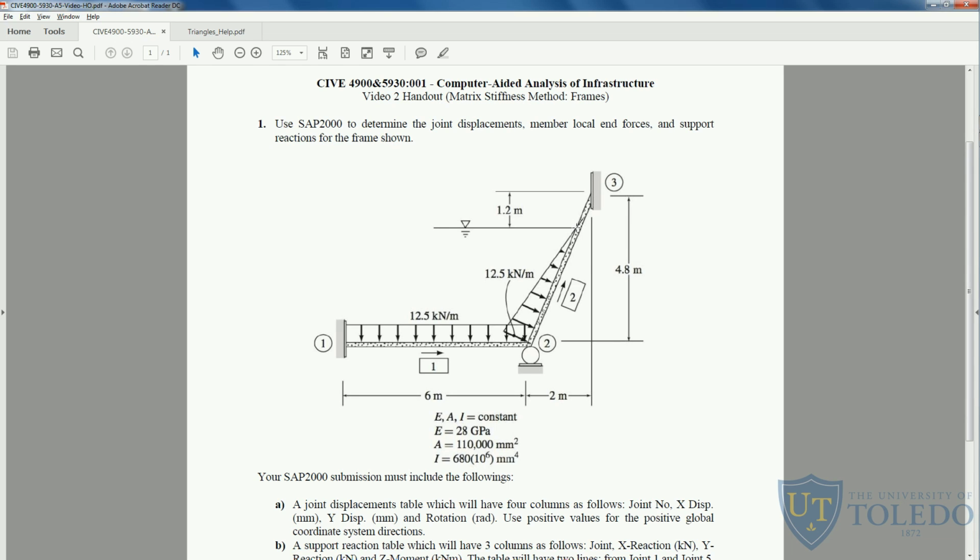So remember, from fluid mechanics, the pressure of the water grows in a triangular shape as the depth of the element increases. So the way we're going to apply that in SAP2000 is using the trapezoidal function of the distributed load. But first, we need to define what is this length that has no applied load, because we will need this to set the points in SAP2000.